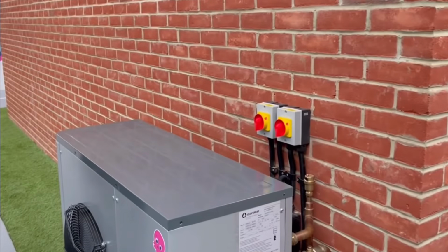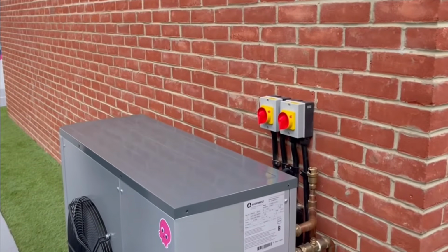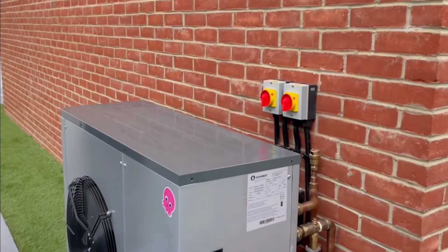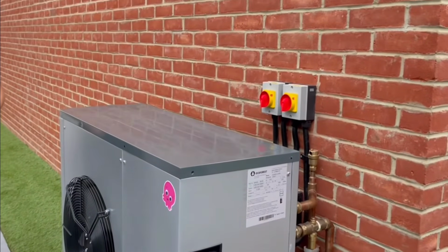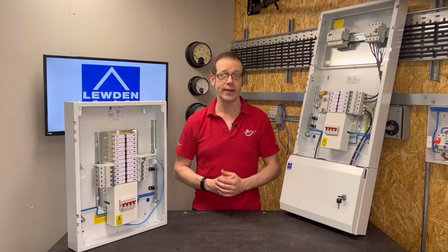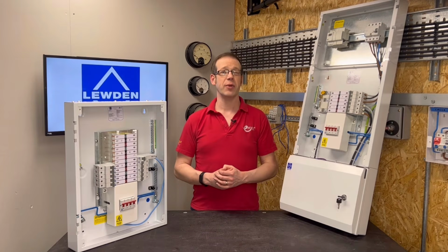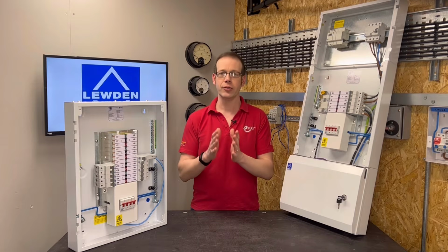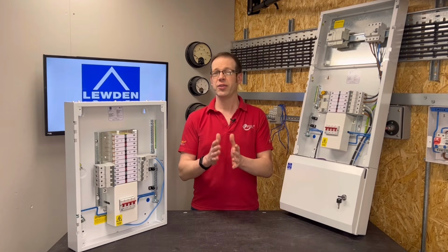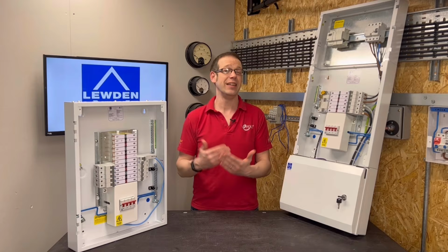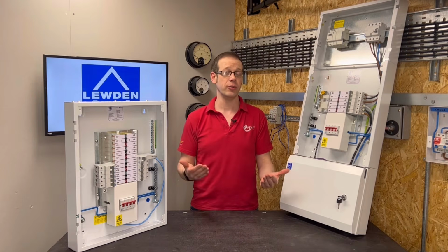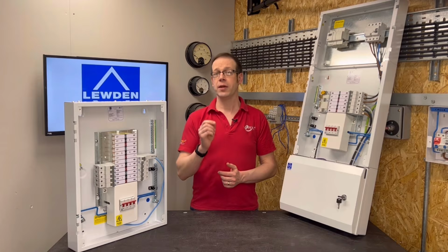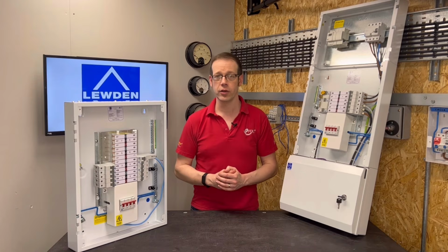With increased electrical loading from EVs, heat pumps and other electric heating, some larger domestic properties are starting to either have three-phase supplies from new or having their existing single-phase supplies upgraded. Up until now, it's really been a question of loading. The benefits of three-phase over single-phase are much narrower on smaller loads, and until now most domestic properties can be considered to be pretty light loads compared with large industrial manufacturing units. But the installation of three-phase to domestic properties may well become an increasing trend over the coming years.